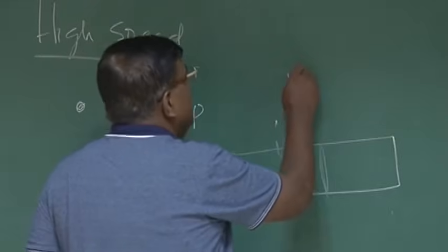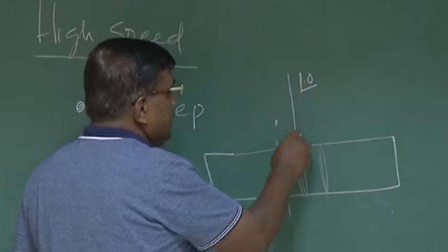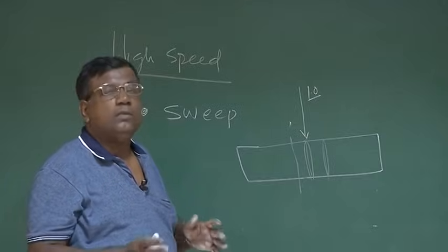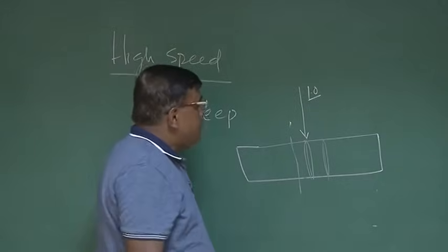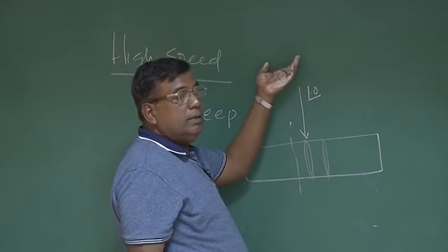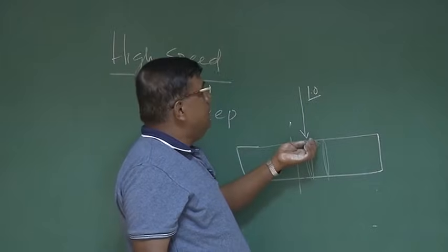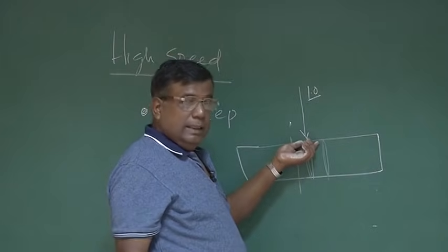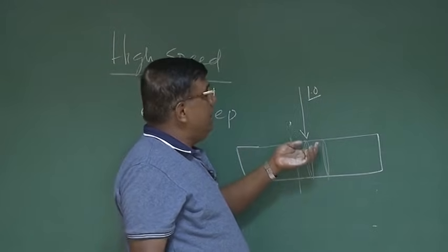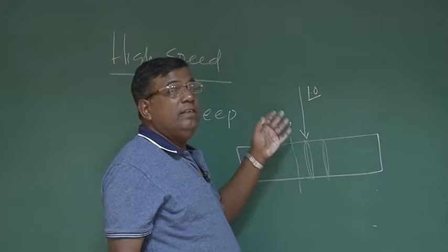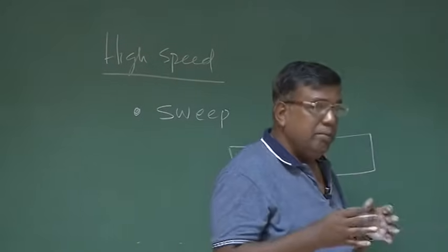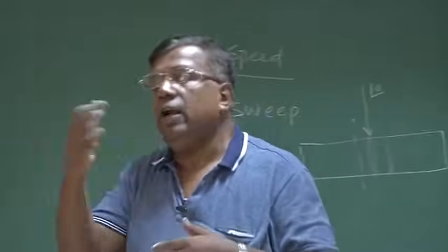So now if it is 1 Mach, theoretically speaking, then this is also 1 Mach, so it is already supersonic. It is coming to transonic, supersonic, they go close. What is our aim? Our aim is that, can you do something so that even if the free stream is around 1, the normal component is less than 1? Then the free stream may be around 0.95 near transonic, but if the normal component to the aerofoil is less than 0.95, then I'm happy. Okay? So I have reduced the effective Mach number, which will decide the aerodynamic characteristics.